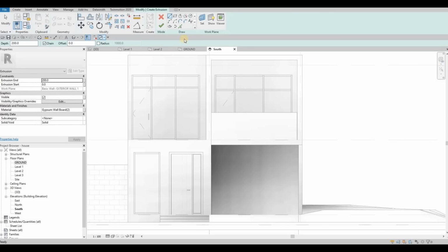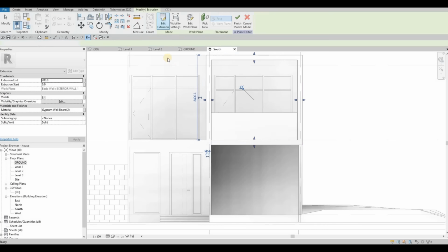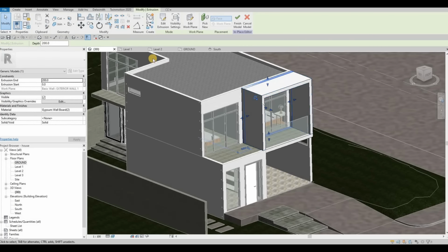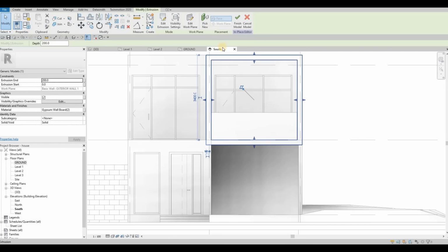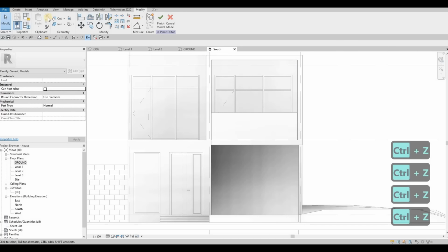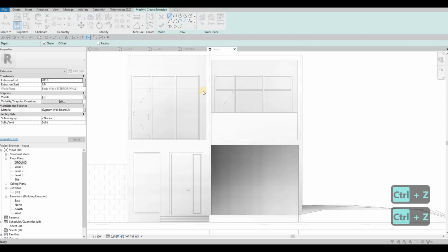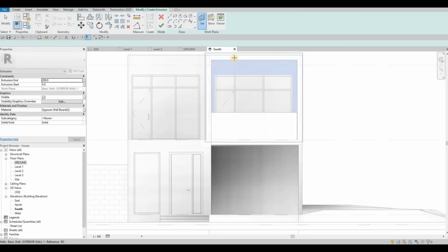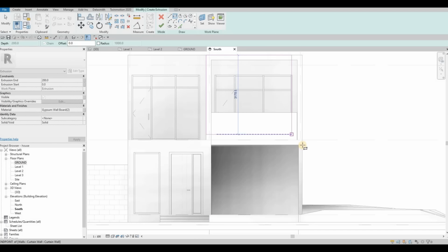I'm gonna create another extrusion, and we could do the same thing, but now it's overall, and we have that perfect gap now, and everything is leveled. Here I'm just gonna undo it, create an extrusion again, and set it. Pick a plane and set it in this plane right here, and then do your extrusion.